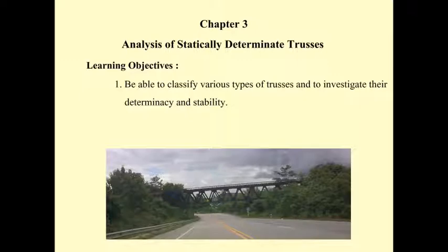And then compare to the number of equations of equilibrium. Each joint of the truss is a pin, and when we analyze the pin, we use the concept of equilibrium of a particle from chapter 3 of Engineering Statics. You know that the equations of equilibrium for one pin are only two equations: summation of Fx equal to 0 and summation of Fy equal to 0.